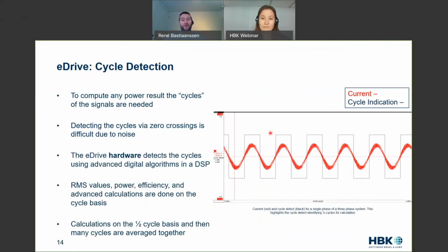But if you want to get more accurate, a very convenient and proven way to get more accurate readings in a stable situation, that's one point that I must stress, is averaging. So each half cycle, we have a power measurement result, and the next half cycle, and the next half cycle, and the next half cycle. So if you take a multitude of those and we average, that is one mathematical way to reduce measurement uncertainty. It's just statistical. So that's why we mentioned that over here.